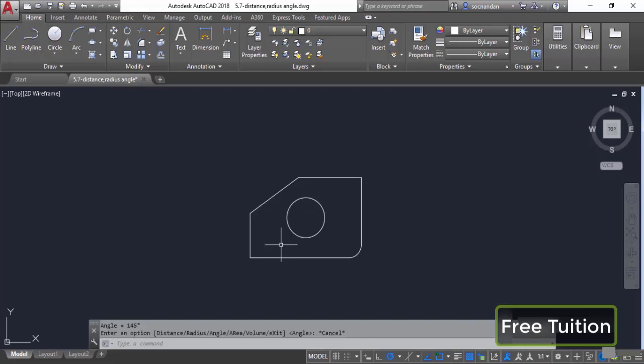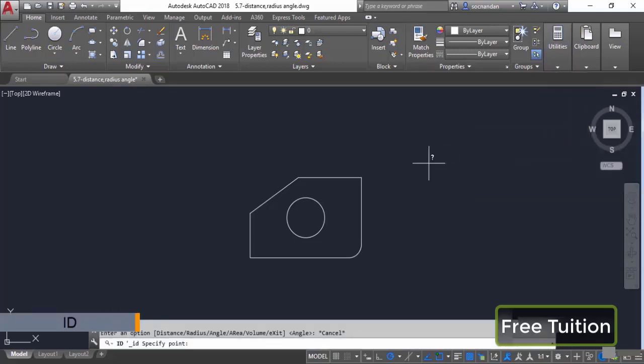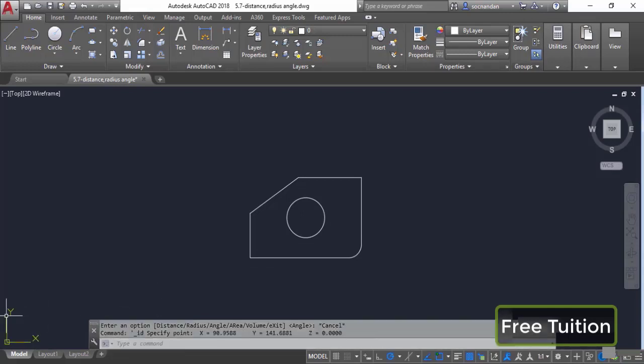Now using the inquiry commands, you can also find the coordinate values of any geometry. For example, in this case, we don't know the coordinate of the center of this circle. And if you want to find that out, simply go to the utilities panel and select this ID point option. You can also use its command equivalent, which is ID. And now click at the point for which you want to find the coordinates. So click here. And now here we have the coordinate value, the x value, the y value, and obviously the z value will be zero as we are dealing with x and y axis only in this case. So in this way, you can find distance, radius, angle, and coordinate values of any geometry using the inquiry tools.